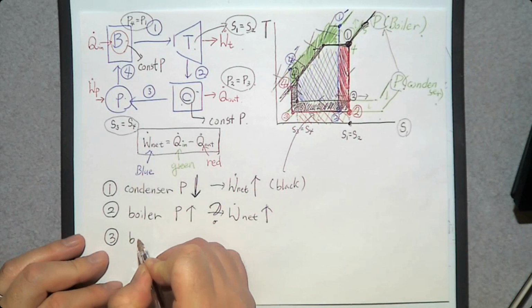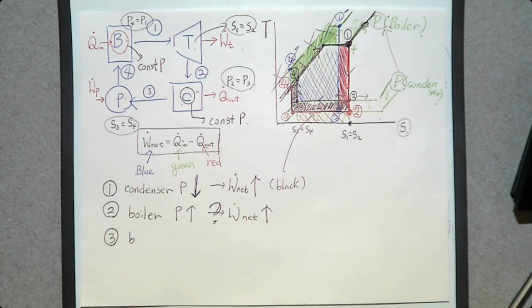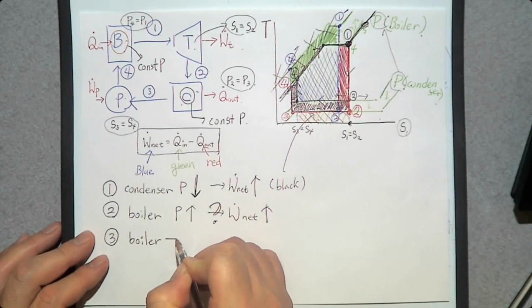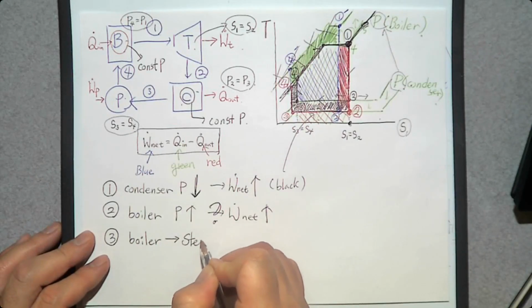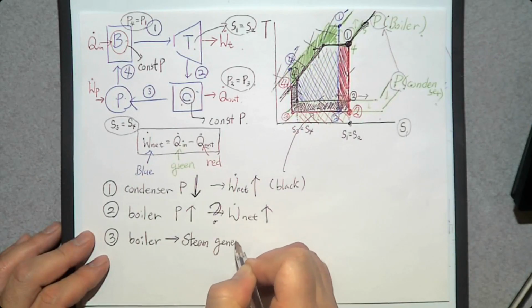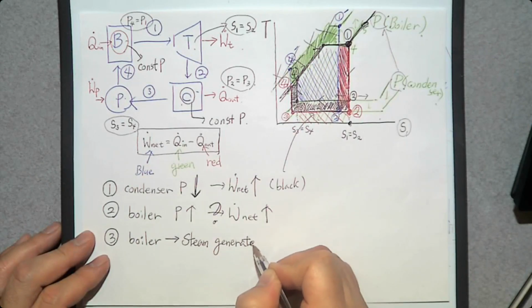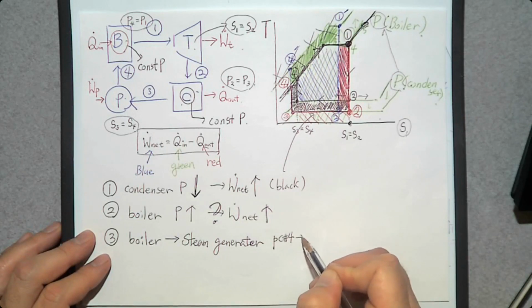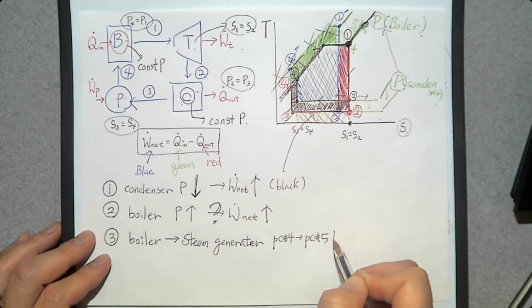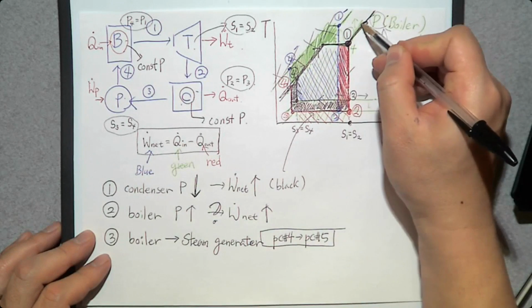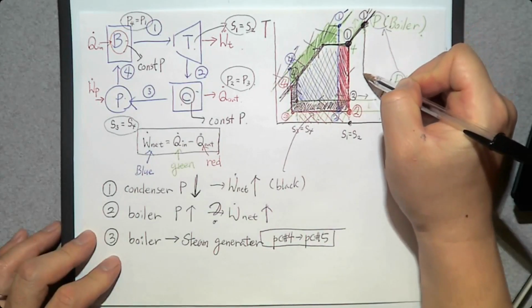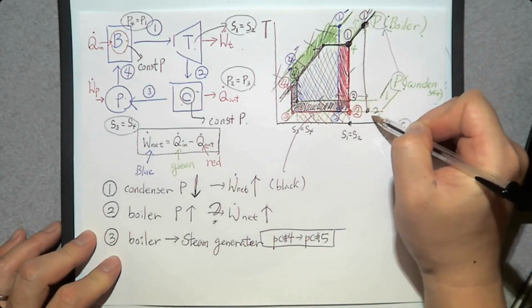So you can, but the name of the device that produces superheat vapor is not boiler. It is a more complicated system. So you are going to switch this boiler to a steam generator. Then phase change process number 4 becomes phase change process number 5. So this one moves up here. New number 1, double prime, goes down by this much. This is new number 2, double prime.